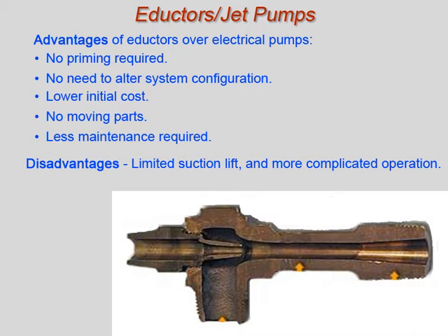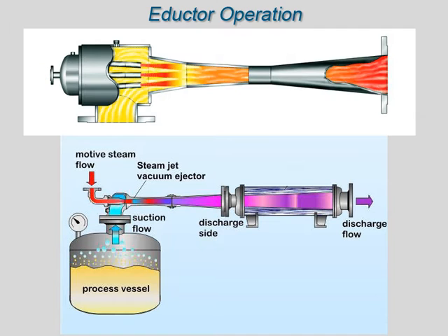Jet pumps continue to be used in LWO, particularly in the tank farms, to transfer waste, move and circulate erosive slurries and corrosive liquids. The terms eductor and jet pump can be used interchangeably. The jet pump uses high-pressure steam. This can be used to transfer fluids such as water, waste, or gases. In some cases, gases are often removed to maintain a vacuum in a vessel, such as a condenser.